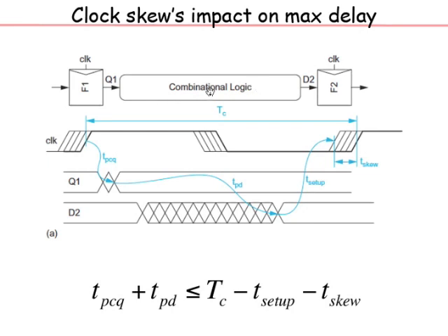Of course, if you fail to meet this timing, that means you have logic. Let us take your FPGA design which you did, and you have all these paths, and it just happens that the delay is more than what this constraint allows. So then what do you do? Well, you have to go back, and you can try very hard to reduce the delay by looking at sizing, looking at layout, maybe making things closer. You have to do those kinds of things. If not, you just have to let go of the TC and say, okay, my TC is going to be a little larger because I'm not able to meet it.